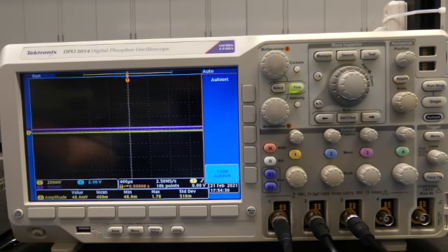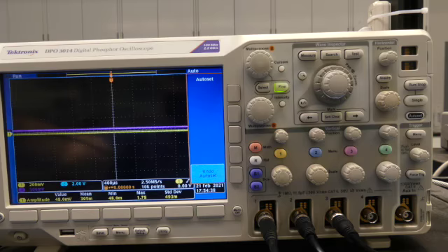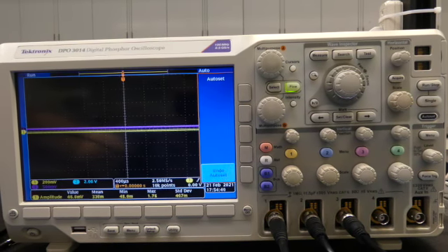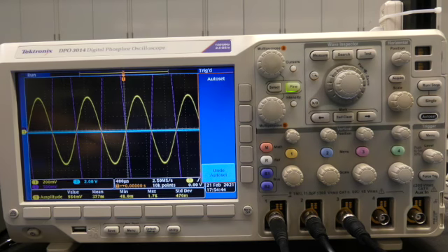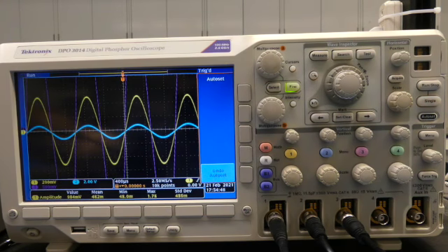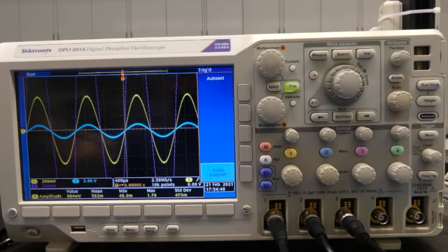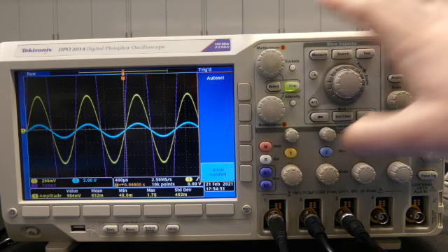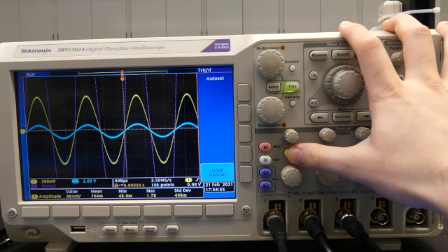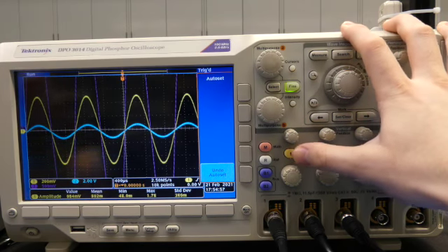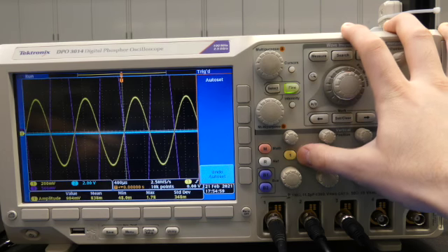I have my DC power supply powered on, so it is supplying positive and negative 12 volts to my circuit where it's needed. And I'm going to turn on my output signals. So you'll see the yellow. First of all, let's go over quick how you should be setting up these channels before I forget. Channel 1 should always be your first AC input.